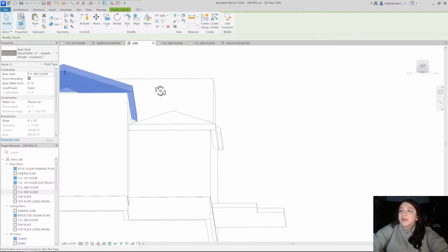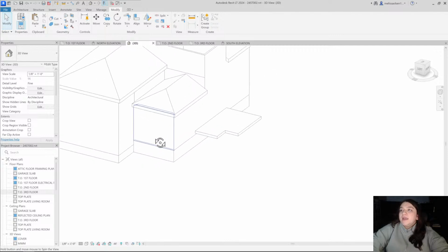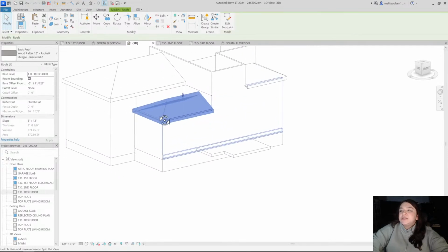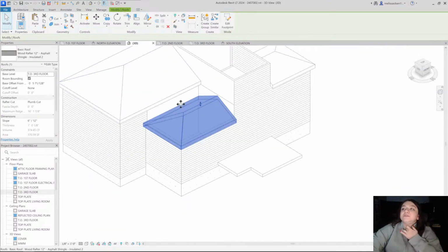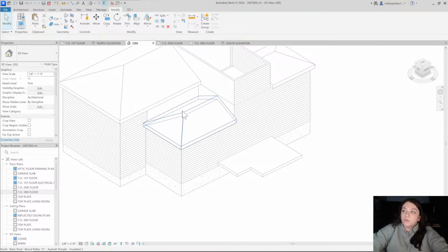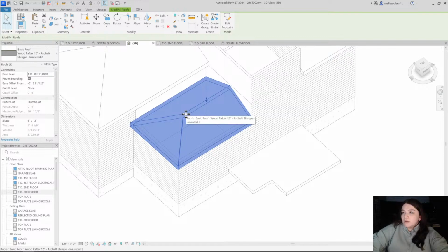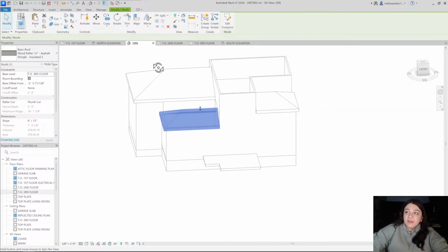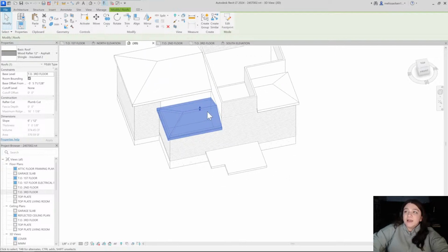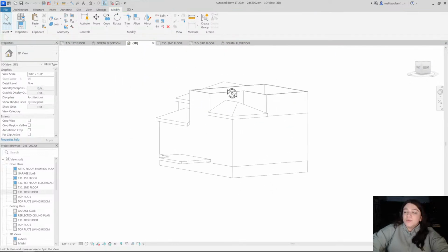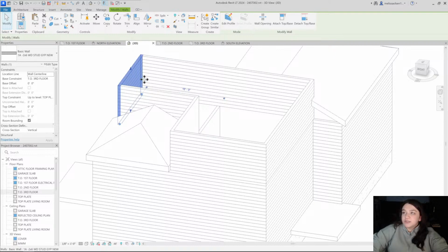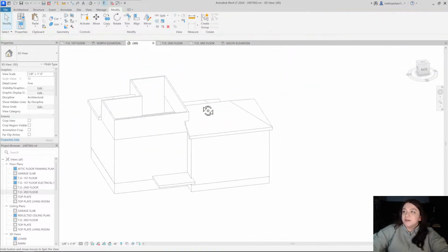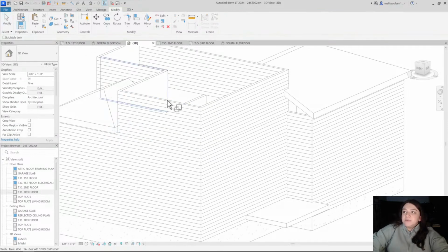We have this 1 foot overhang above, and we're gonna have to change this roof just because, even though now there's a wall here, it will still be collecting snow up against this wall. So what we're gonna want to do is change the roof here. We can get into that at a different time because we are running out of time today. I am hitting spacebar just to flip all my exterior walls so that the exterior material is on the outside. I'm going to join these walls that we have stacked on top of each other.